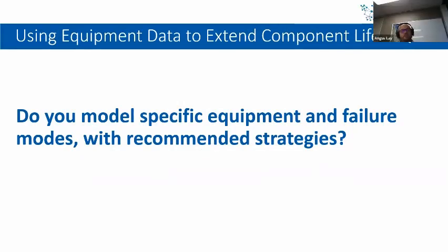Yeah, look, this question: do you model specific equipment and failure modes with recommended strategies? Absolutely. I could speak to a real example where we had a specific failure mode on a fleet of equipment, and through exploring the driving factors, we found that it was another component that we needed to change strategies on to ensure the engine made the extended life we were looking to achieve with minimal downtime.